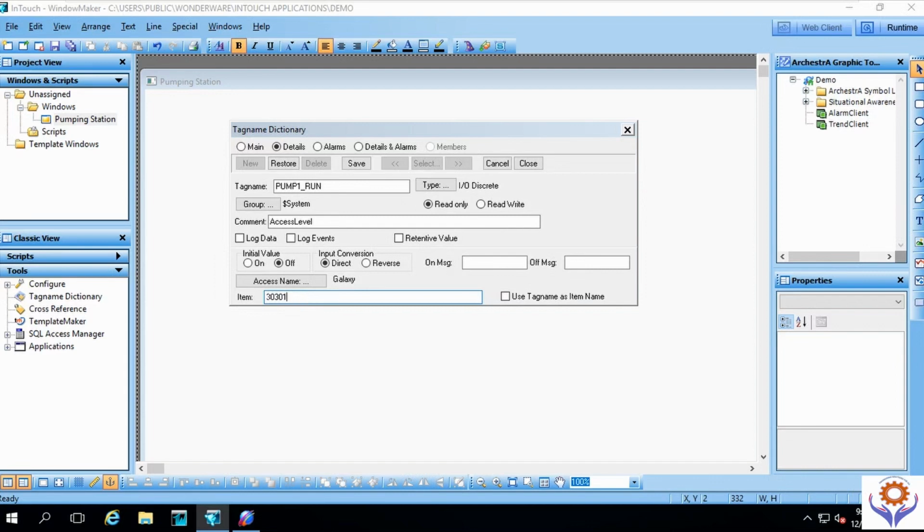But you are not using the memory word here, you are using the memory bit. So you need to give here, for example, 3001:1. See, you need to first understand these registers. Some of them will come as :1, some of them like .16, .12 up to 16, based on how you are using the functionality and the IO servers.